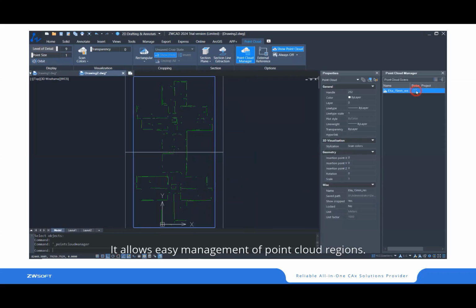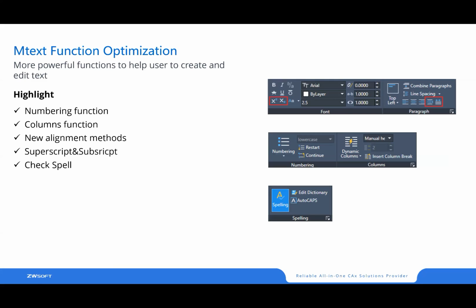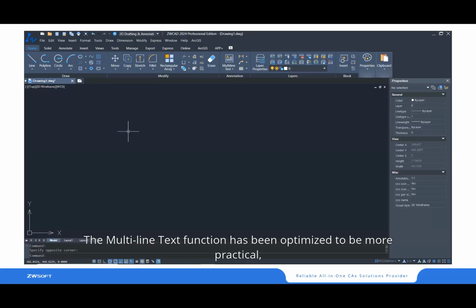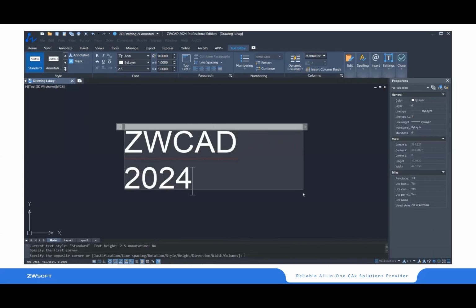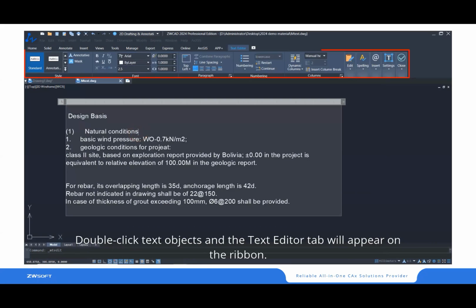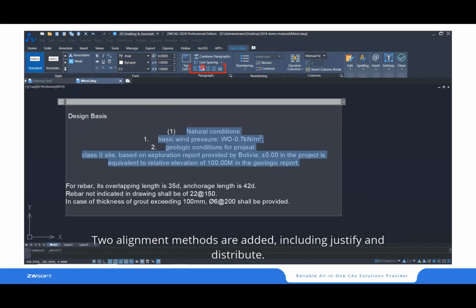And we also have the section plane to create a section cut to the point cloud file, like it shows in the video, how we can cut through the building plan. We can also adjust the height of the section cut. So we can decide which floor we want to cut through the building. And with the section line tool, we can also extract the line work to create a floor plan drawing based on the section plane, so that you don't have to draw or trace the building walls. ZWCAD will automatically generate the walls for you so that you already have the building plan.